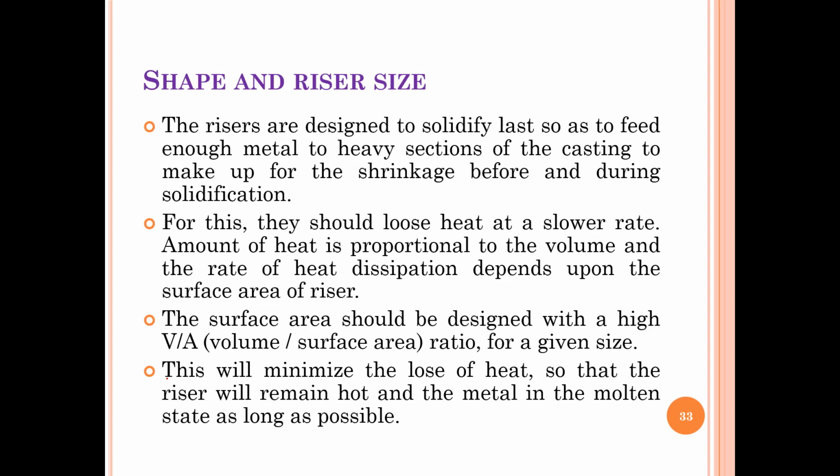The amount of heat is proportional to the volume, and the rate of heat dissipation depends upon the surface area of the riser. The riser should be designed with a high V by A, that is, volume by surface area ratio for a given size. This will minimize the loss of heat so that the riser will remain hot and the metal in the molten state as long as possible.